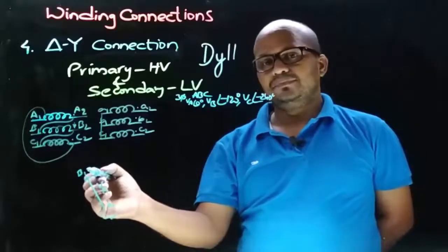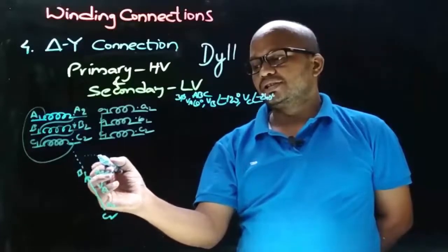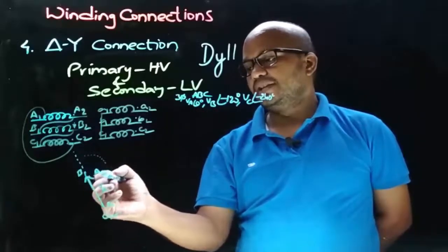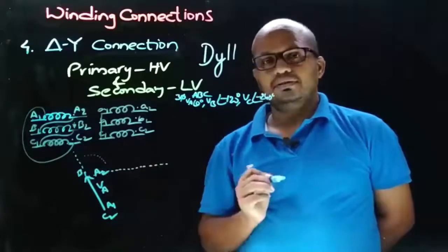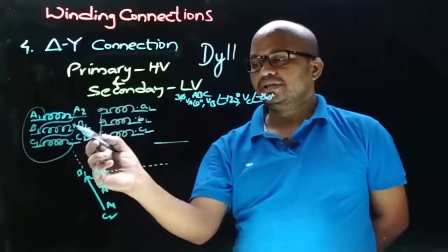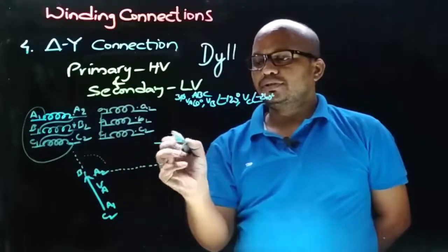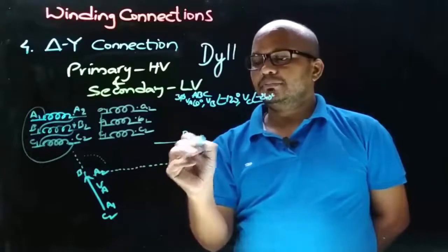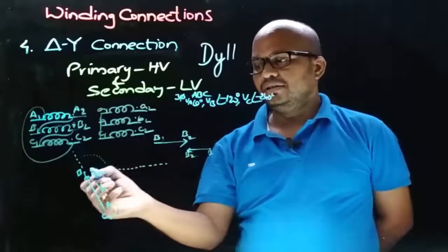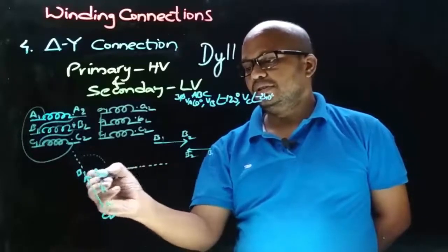So if this is the VA phasor, now in the clockwise direction, because of minus 120 degrees, there will be the VB phasor. So let's consider this as the VB phasor, and observing the winding connection, on the primary side the external connections are taken from dot end terminals, therefore the arrow must point towards the dot end terminal, therefore this must be B2 and the other end must be B1. So now place this VB phasor such that A2 will have B1, therefore the VB phasor will be like this.